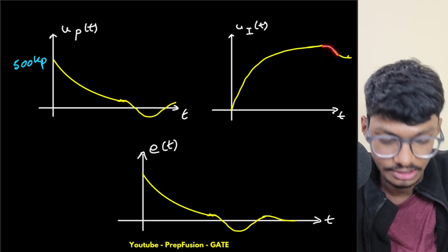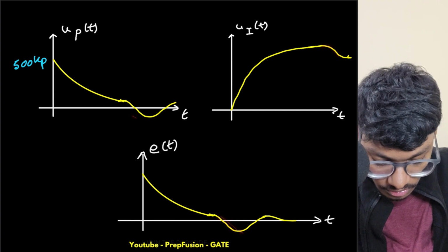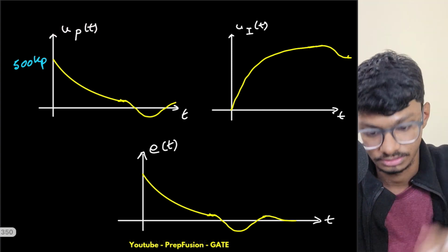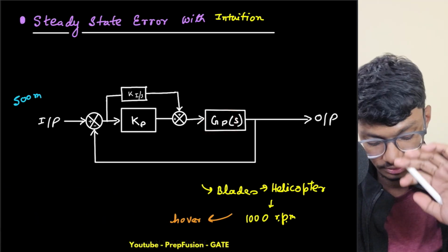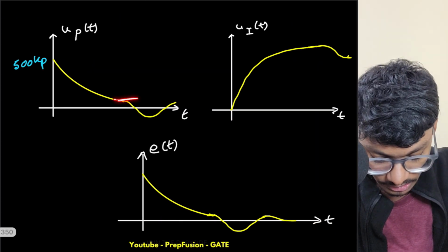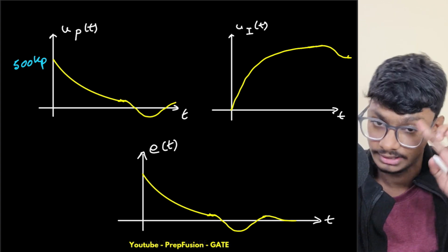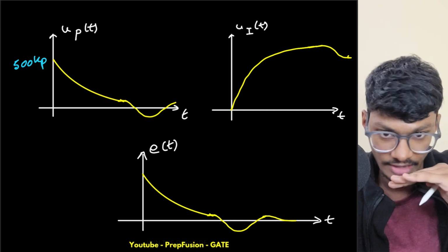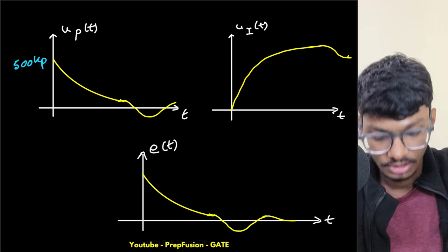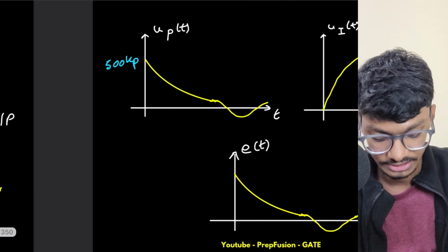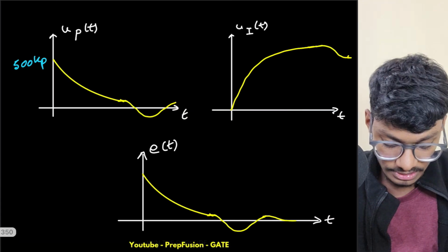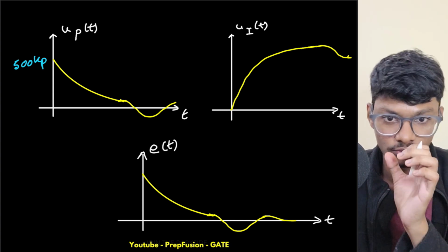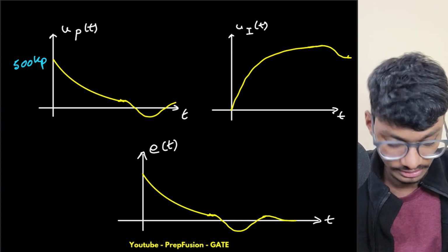Now it will slowly start reducing, because the area is reducing, and this proportional control is also giving me some negative output, telling it to reduce your speed. Earlier, proportional control was telling it to have a constant speed, like that previous case of 1000 rpm constant speed. But in that region, the proportional control was telling it to have a constant speed while the integrator was telling it to increase speed, hence overall it was increasing its speed. That is why the error was reducing. Previously the error wasn't reducing, because it was telling the motor to have a constant speed, and hence the error was also constant. Now this is telling it to reduce the error. So that is what is basically happening over here.